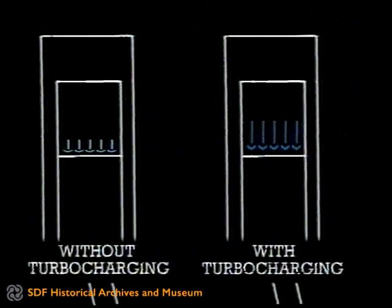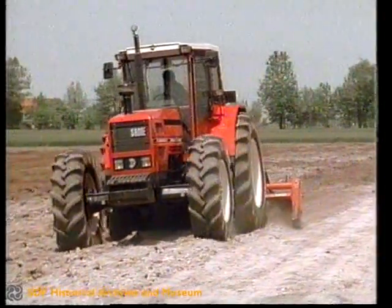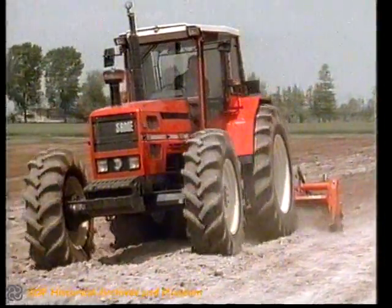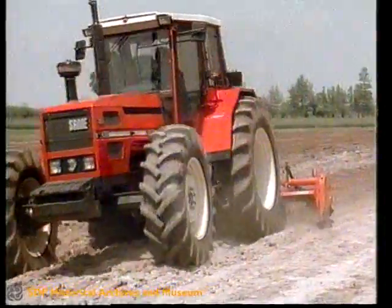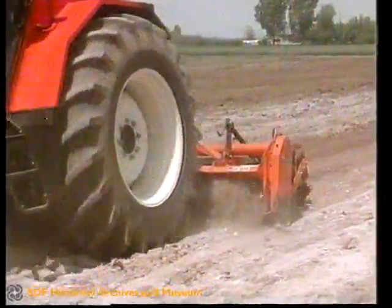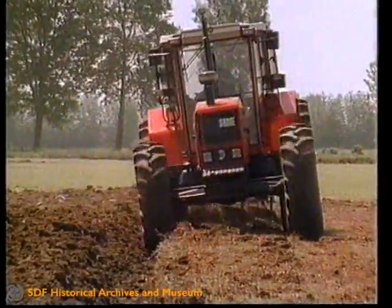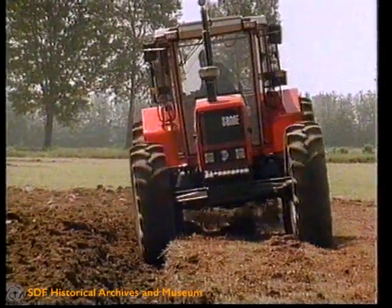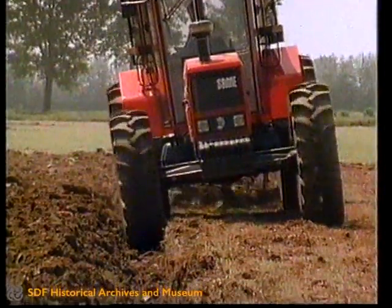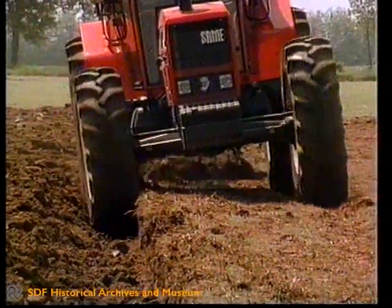Results: increase in power without increasing the cylinder capacity, the weight, the size, or the maximum speed. Finally, increase in the specific output power, which is the power per unit of cylinder capacity. Improvement in engine resilience. Lower specific consumption compared to an engine of equal power which is not turbocharged. Compensation for loss of power at higher altitudes. Less pollution due to better combustion, less smoke emission associated with the improved air-fuel mixture. Quieter.